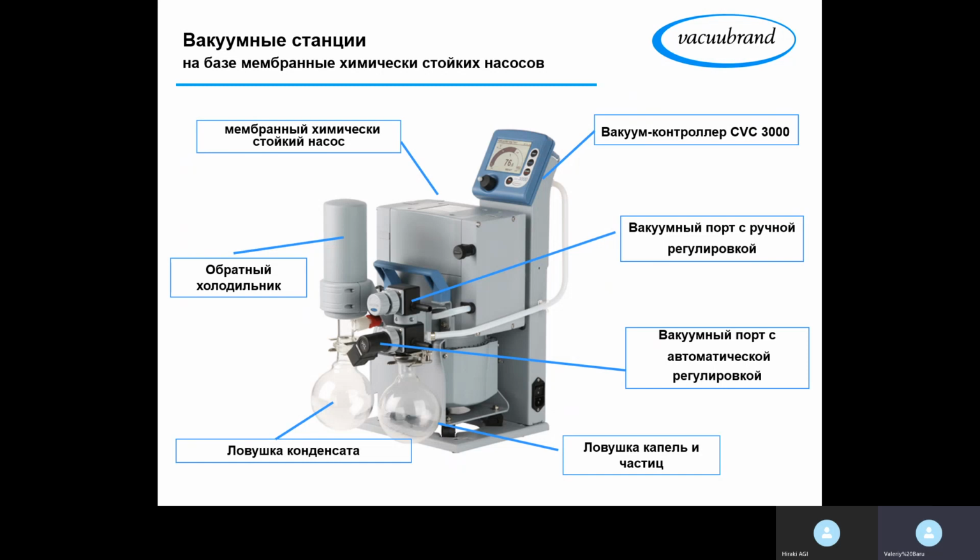So what you can do, you can have your tube which goes from the applications through the wall to a safe area where you have the vacuum pump, and you can have another tube which goes from the outlet of the pump back to the explosion-proof area, the explosive area.